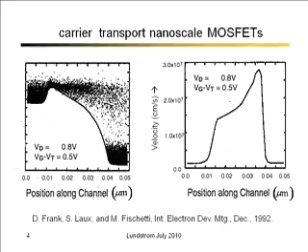Well, a lot of our understanding and a lot of the design that gets done in companies like Intel and others uses very sophisticated simulation programs. This is a Monte Carlo simulation, some results that came from IBM a number of years ago when they were looking ahead. And this is a semi-classical simulation, so it's a simulation that treats electrons as particles. What you're seeing on the left is the conduction band versus position for a hypothetical, I think, SOI double gate transistor with a 30 nanometer channel length.